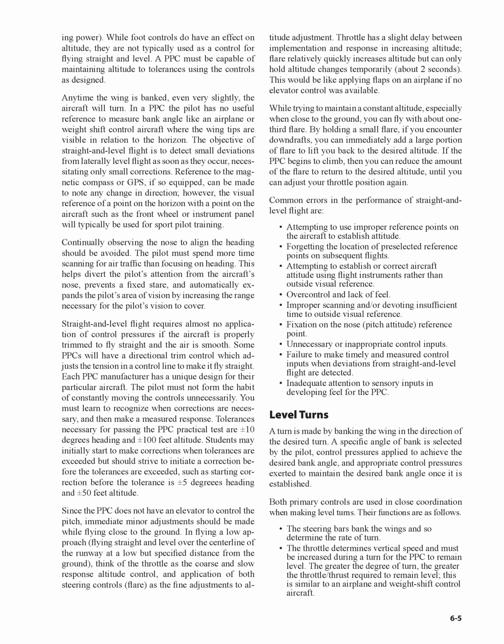Since the PPC does not have an elevator to control the pitch, immediate minor adjustments should be made while flying close to the ground. In flying a low approach, flying straight and level over the centerline of the runway at a low but specified distance from the ground, think of the throttle as the coarse and slow response altitude control, and application of both steering controls, flare, as the fine adjustments to altitude adjustment.